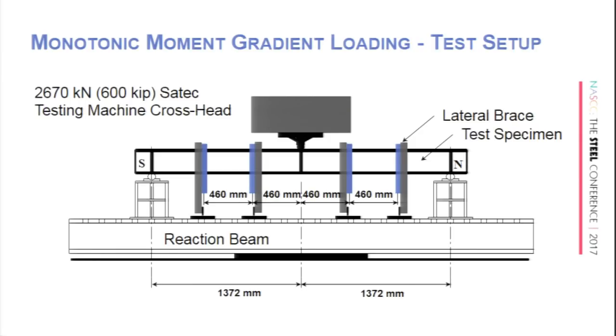So there is the brace spacing for this beam, which is, I can't do this math anymore. These beams are fairly long, 12 feet. The brace spacing here is to ensure that my bracing is close enough. And if you saw in the pictures that Craig showed, we have Lp and Lr along that unbraced length.